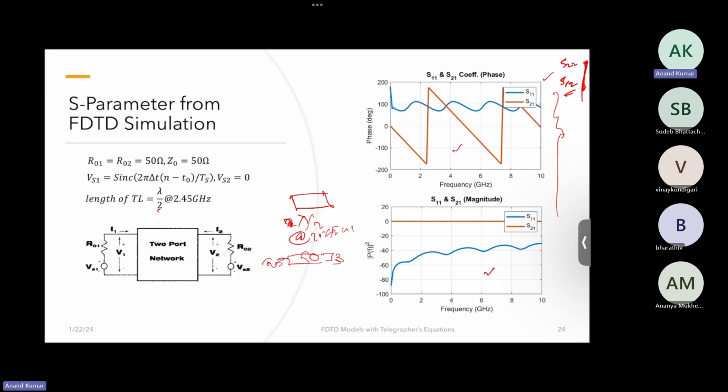Since there are no elements on this, we have S11 much below. This means that all the power transferred from the generator to the load because everything was matched, and as the S21 is 0 dB, this means all power was transferred, and almost negligible power was reflected.